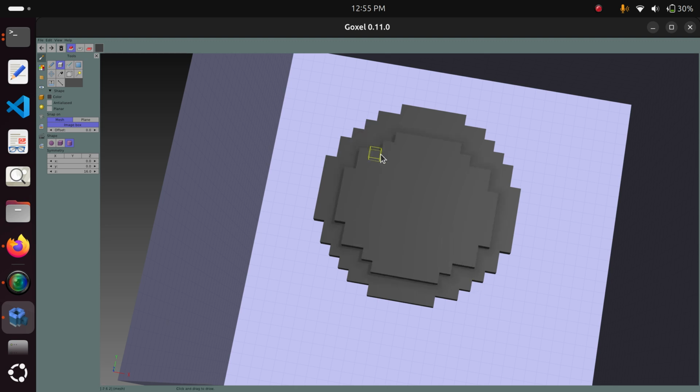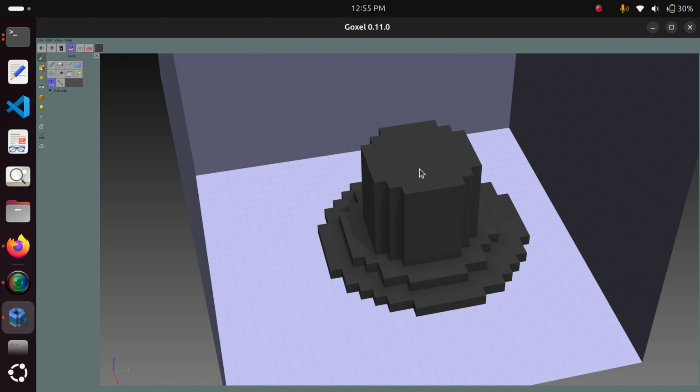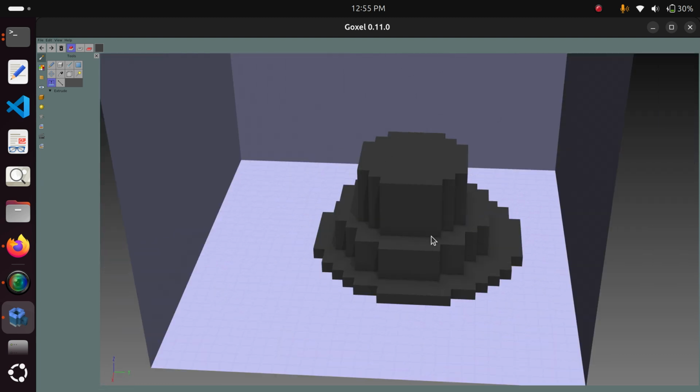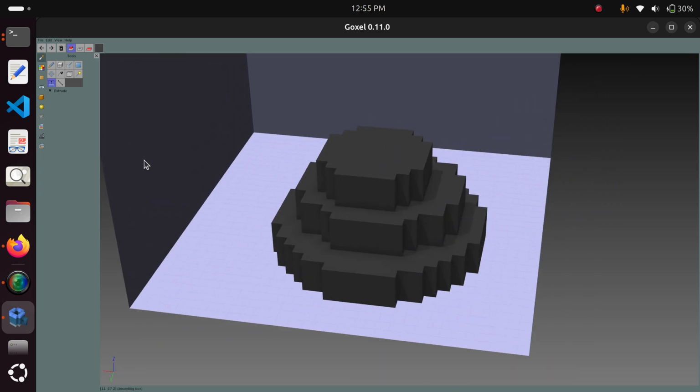What we're trying to do here is simulate levels on the stone. There's this extruding feature within tools where we can extrude the material upwards by using our mouse. We're going to extrude the innermost circle, then the next one, and this one. And that should be the stone.